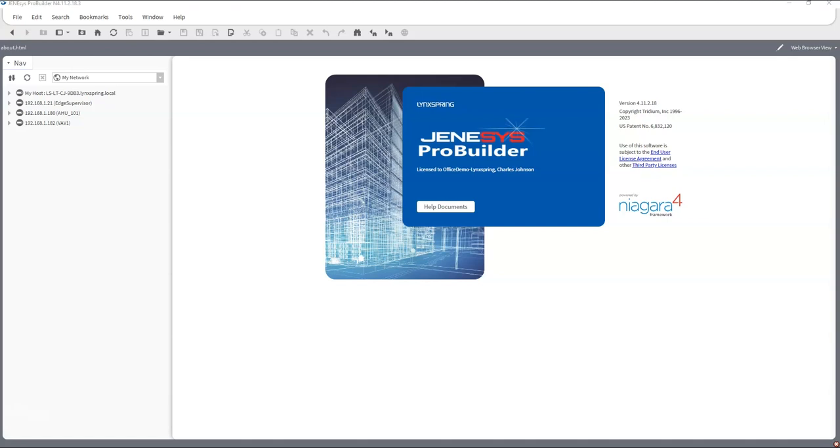This graphic is going to contain a pop-up window to configure any of the local VAV commissioning settings. We're going to go through that. And of course, as each VAV completes its commissioning, a report is going to be generated and sent to the supervisor. Then each supervisor zone has a commissioning manager graphic to monitor the zone commissioning activities. Configuration settings for the zone commissioning manager include providing the week, weekday, and time by the hour for when the commissioning cycle should start each month.